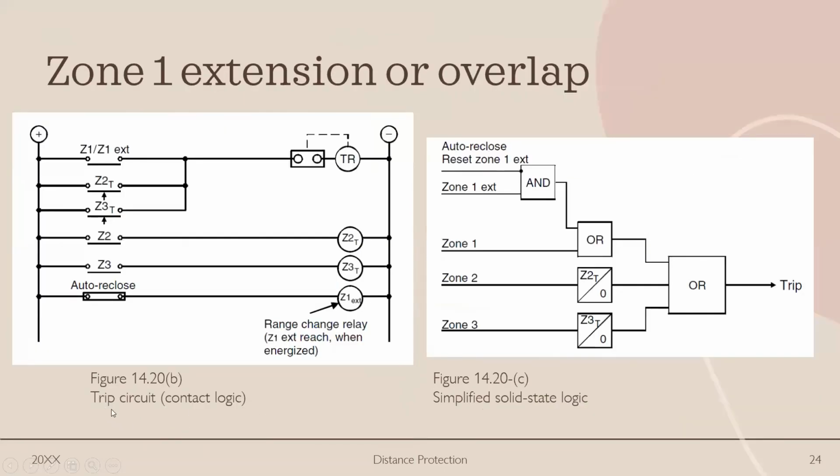Of course, we also have the trip circuit logic, wherein we now have zone 1 extensions here and here. And for the simplified solid state logic, we auto reclose reset zone 1 extension here.